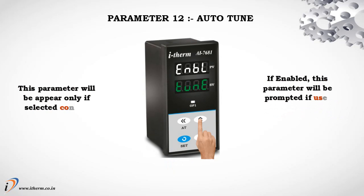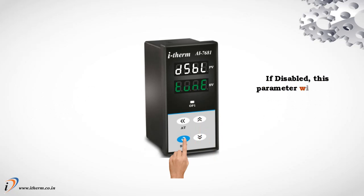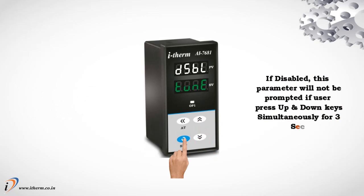Parameter 12, auto tune. This parameter will appear only if selected control action is PID. If enabled, this parameter will be prompted if user presses up and down keys simultaneously for 3 seconds. If disabled, this parameter will not be prompted if user presses up and down keys simultaneously for 3 seconds.